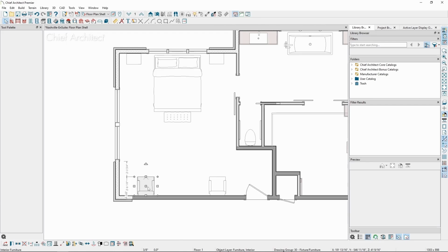If we have bumping pushing snaps on, and we try to push this up against another object or a wall, we can see that we now have an extra buffer zone that's being enforced. If we've added one of these buffer zones, but we want to bypass it temporarily, we can just turn off snaps. By holding Control on your keyboard, or pressing Command if you're on a Mac, you can temporarily turn off all snaps, allowing us to move the object closer to the wall, ignoring the buffer zone. But if we push any objects up to it while no longer holding Control or Command, it's still pushed back by the bounding box.